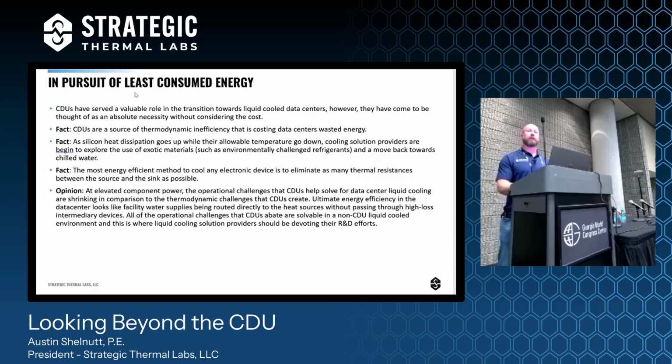Absolutely. So there, again, feature sizes are dropping because we want surface area. Cold plates are two-dimensional heat transfer devices today, and the best way to get more surface area is to shrink the microchannel hydraulic diameter, right? As small as we could possibly go within the realm of manufacturability.